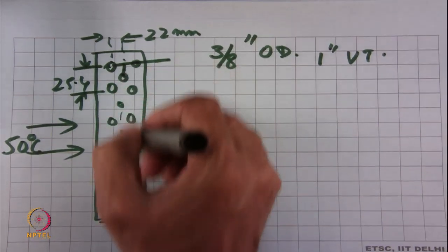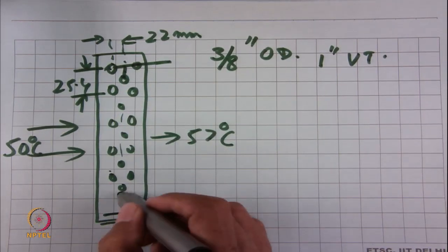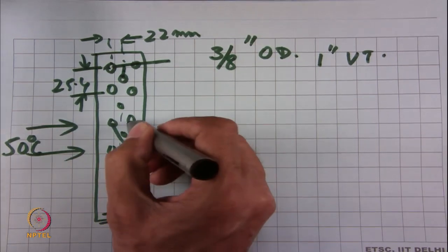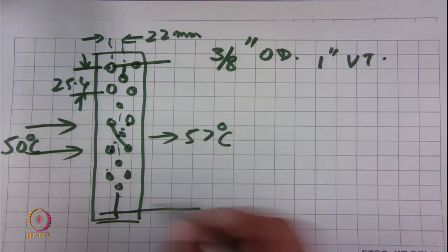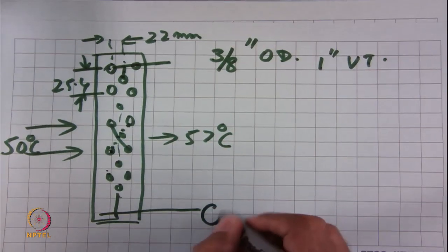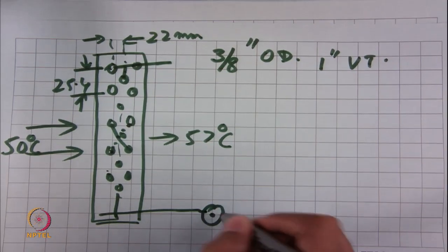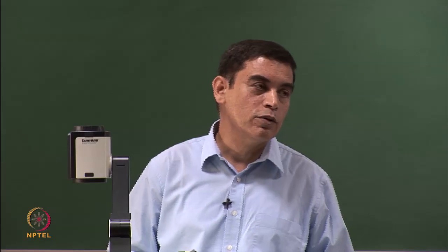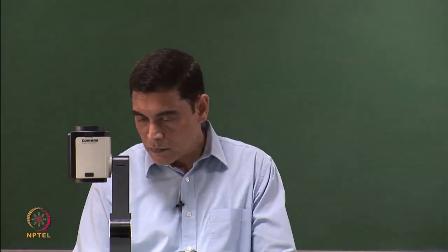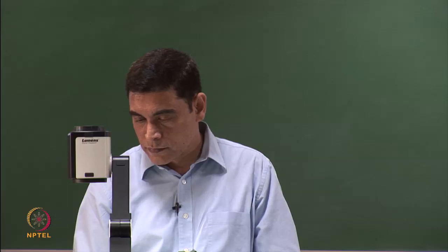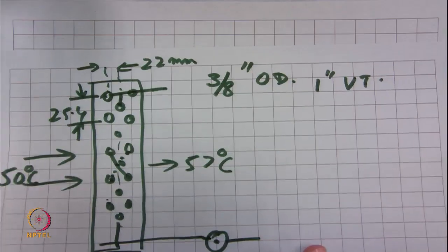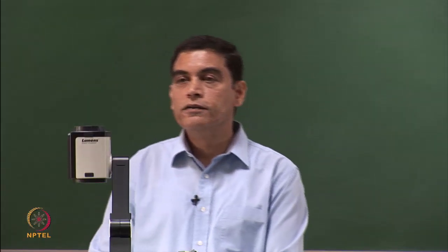So, one circuit we would just get right down into a header here, and these we would swap midway. So, this tube would connect here and this tube would connect to the other side, and again we would put in a side glass with a moisture indicator right at the bottom of this coil to be sure that when we are charging refrigerant, we are having liquid, subcooled liquid at the outlet of the condenser. So, with this done and the capillary selection arrived at by some experimental means, we had a product ready for testing.